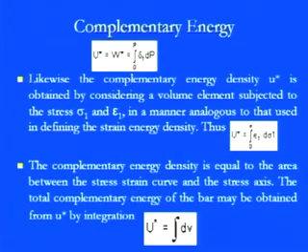So for the complementary strain energy we found that the domains are somewhat different from the normal strain energy, or we can say the elastic strain energy. That's why we were discussing in the initial phase that if we are talking about the linear elastic region, then the complementary strain energy and the elastic strain energy must be the same, because whatever the domain is, they will simply have a linear relationship, irrespective of whether it's a strain domain or a stress domain. Since they have a proportional relationship, there is no difference as such.